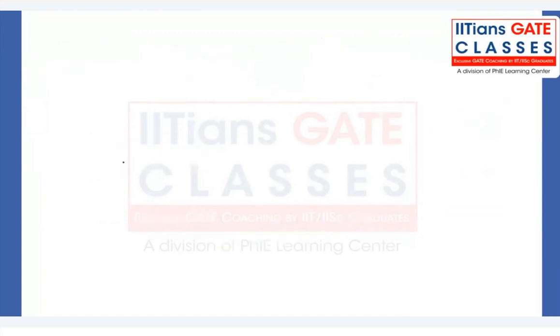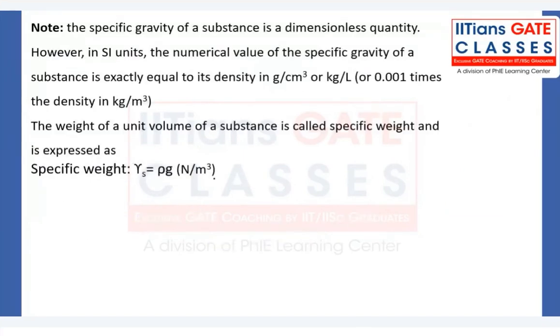Now coming to the next topic, specific gravity. Whatever we have learned, does it have some unit, or is it a dimensionless quantity? It is a dimensionless quantity, right? Because specific gravity is what? Rho of any fluid or liquid to rho of what? Density of water. Here also kilogram per meter cube, here also kilogram per meter cube. So that's why we are saying it is a dimensionless quantity.